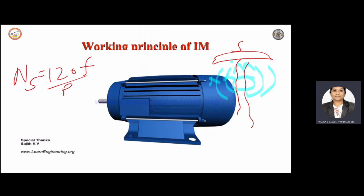Let us assume there is flux in this direction, flowing between the north and south pole, and this is the conductor in blue. Some of the fluxes here, in the same direction, get added up. In this direction, the conductor flux is opposite to the main flux, so it gets cancelled and is zero. So on the right side it is zero, and towards the left side the fluxes add up.